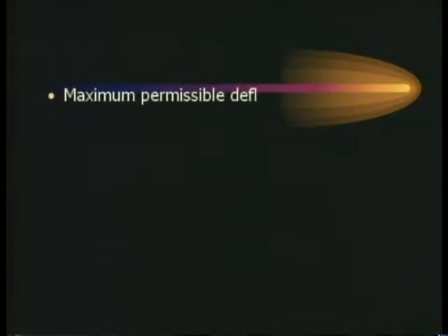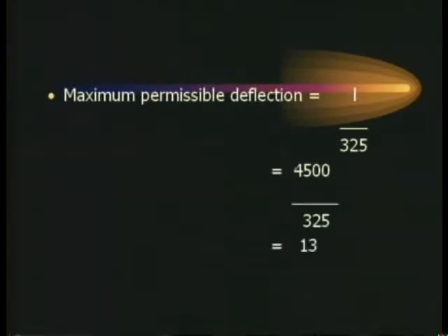You have to check for deflection. And what is the maximum permissible deflection? It is L divided by 325. That comes to 13.8 mm.